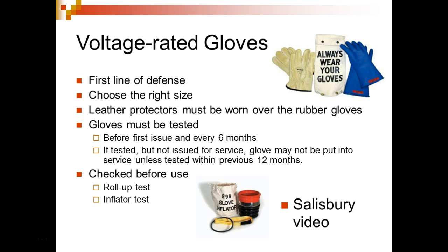So fuses, when you fuse a motor, you have to fuse it to allow it to start. So it's usually about 150% of the start current. That way the motor will start without popping a breaker or blowing a fuse. So what's required on motors is some type of overload protection, which means it's supposed to have something in that motor that will kick it off if it draws starting current over a certain amount of time. We call them overloads, and that's required.